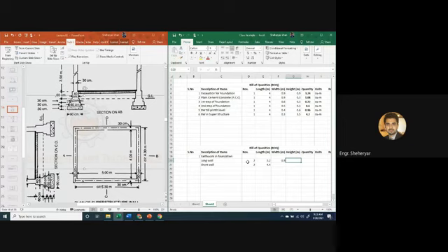Yes, sir. And what is the height? 0.3. No, by height, the item in consideration is the upward in the foundation, which is the excavation. So what will be the height, or depth, of excavation? 0.9. Look at this. The ground level is at this level, so you will excavate the ground from this level. So 0.3 plus 0.3 plus 0.3, this is 0.9. Same for these as well.